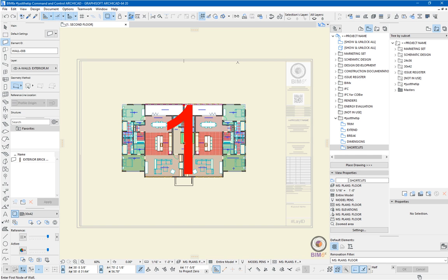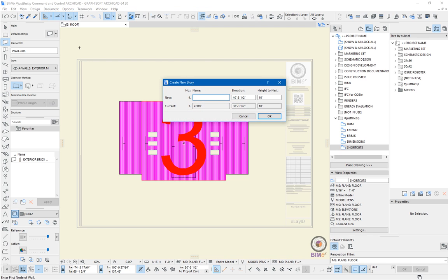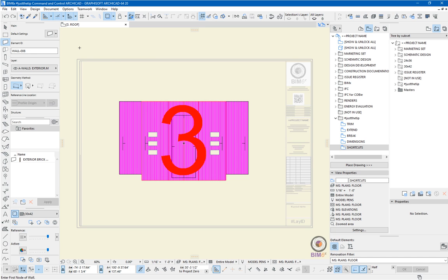And what that does is, thanks to my very subtle numbering system here, move me up to the floor above. You can also see the naming and the numbering on the name of the tab up here. So Control, up arrow, again takes me up another floor, and again takes me up to the roof. And if we try and go too far, what it'll do is prompt us to create a new story. So I'll cancel that. To go back down, I'll give you 3 guesses what the shortcut is.